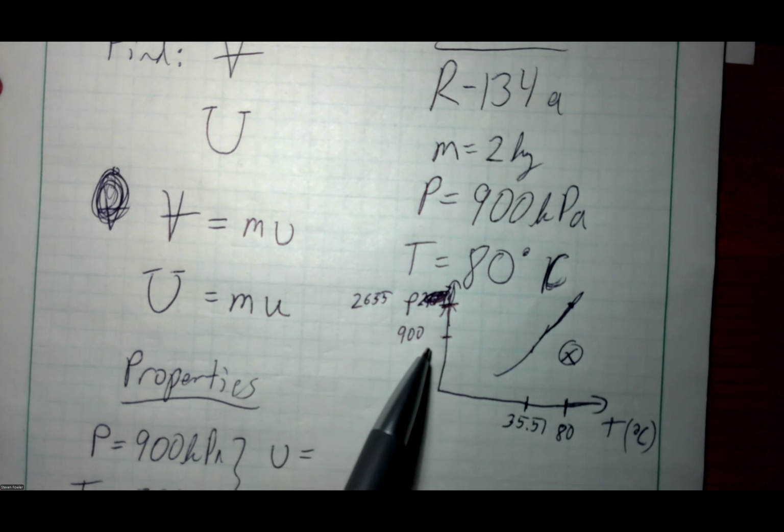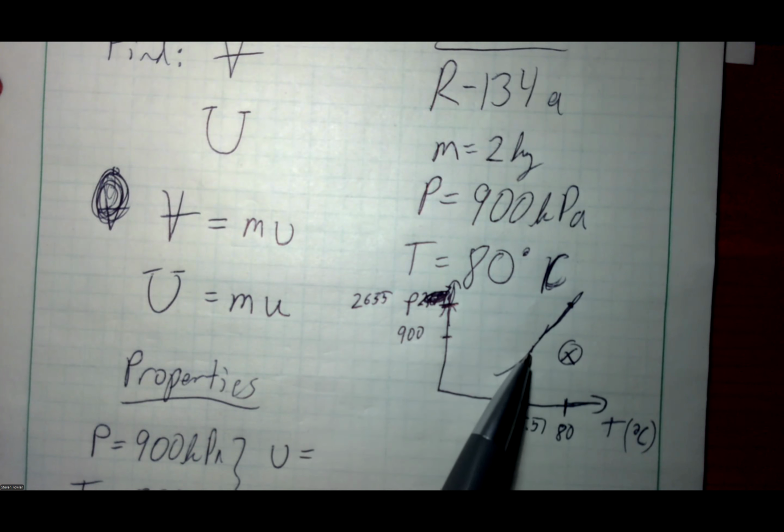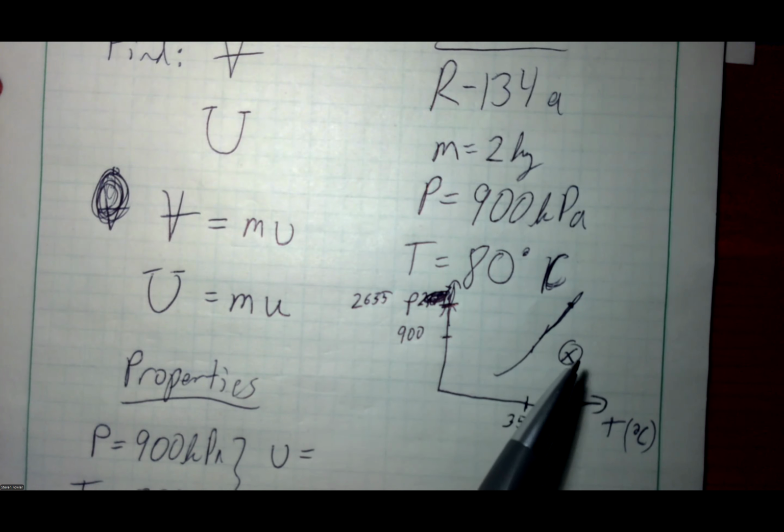I find it much easier to say, hey, given the pressure, go look up the saturated temperature. Are you beyond the boiling or the saturated temperature? That puts you boiled off. You're over here in the superheated vapor region. That's how I think about it.